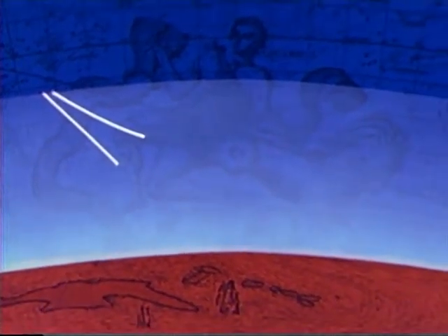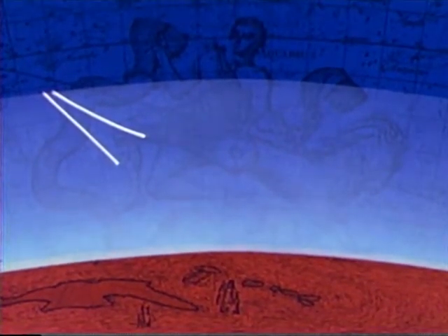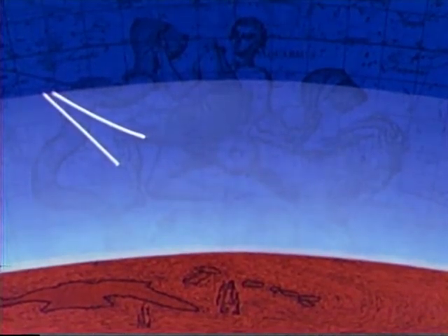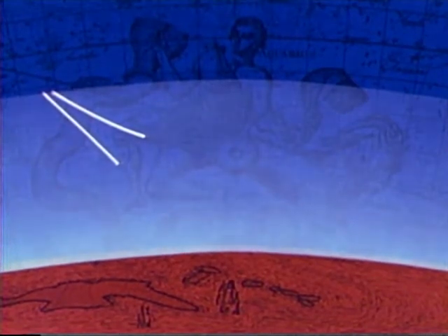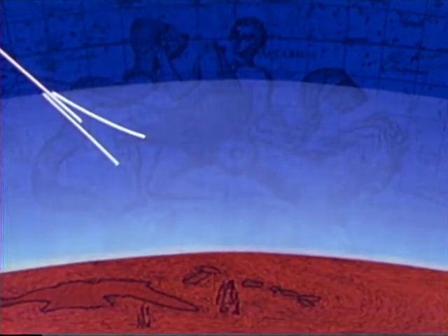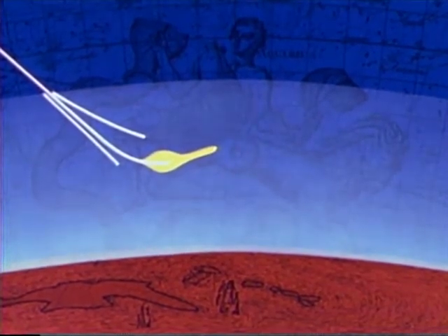Once the command module enters the atmosphere, it has about 1,000 miles and a bit over 2.5 minutes of controllability divided into 2 brief control periods. Most of this controllability will be used up during the first control period. The trajectory the command module will follow is basically as follows. It will enter on a given flight path and proceed downward to the pull-up point. Just before pull-up, it enters the atmosphere dense enough to allow aerodynamic control of its landing point and begins its first control period. The command module will then climb until it skips out of this denser atmosphere.